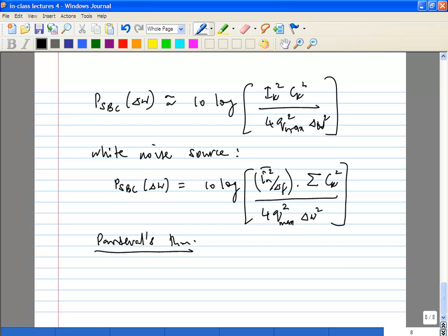So remember Parseval's theorem. If you sum the modulus of all your Fourier series coefficients, that will be the same as the power in the signal, right? So if you do that for gamma, you can show that this is equal to 2 gamma RMS squared. Okay.